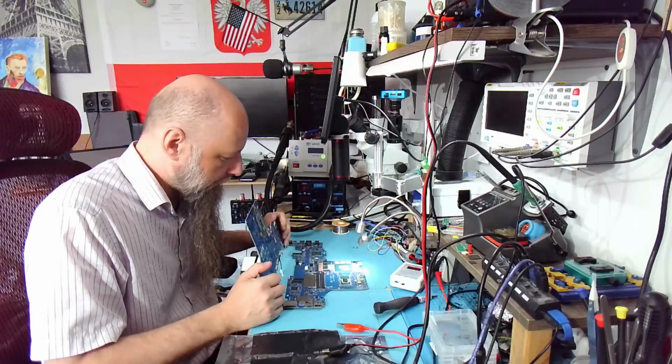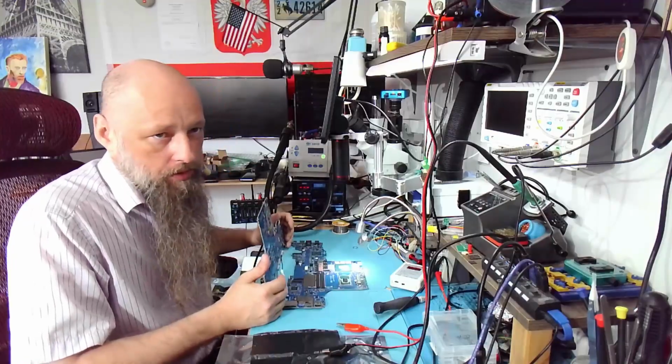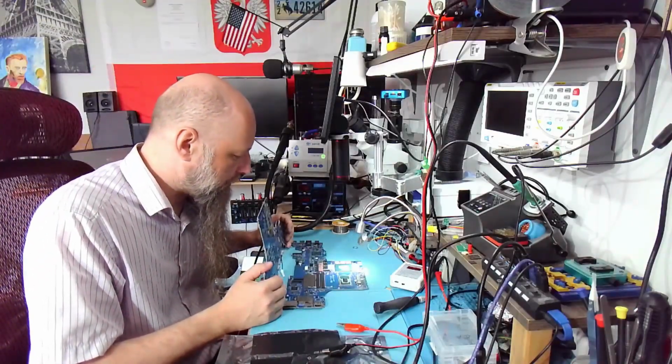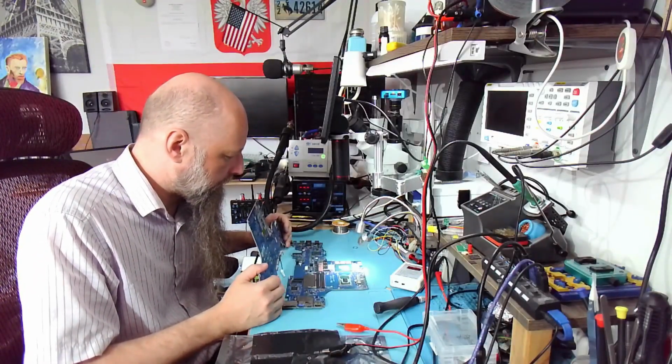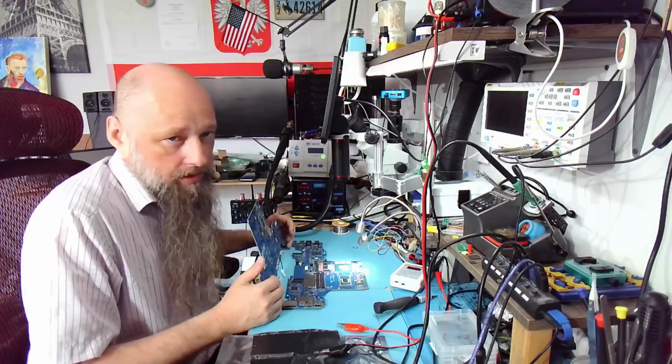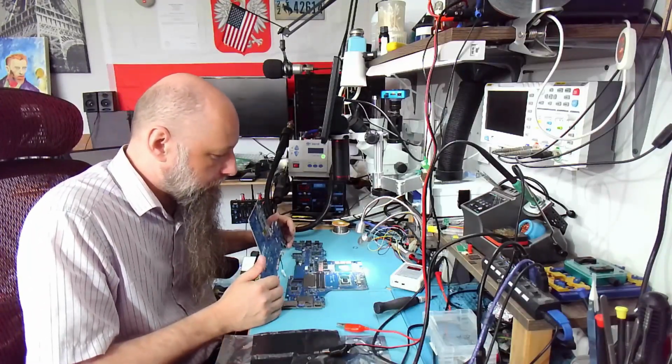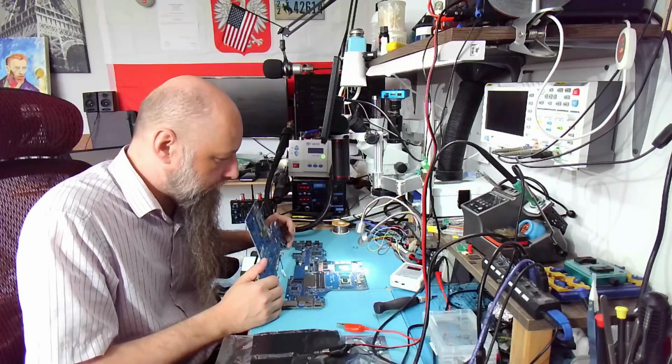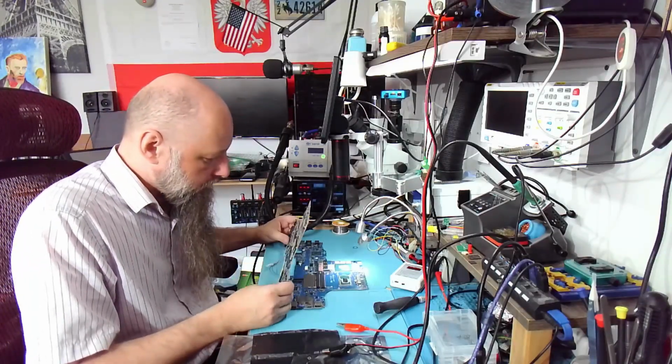If there was anything that I see around the GPU, or a short or anything like that, then yeah, we could find it. But no, there's no shorts on VRMs. The core resistance seems okay, so the GPU seems to be fine, electrically at least.